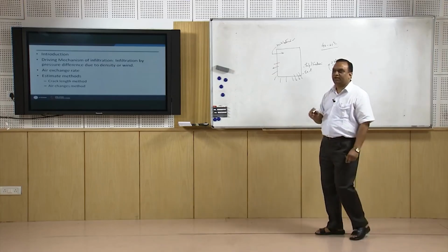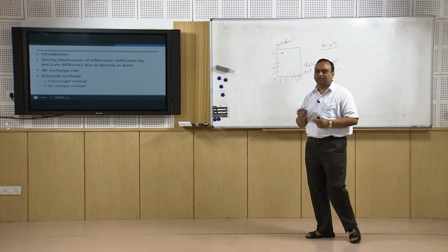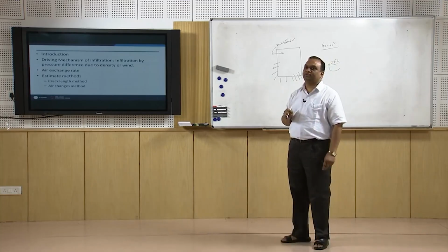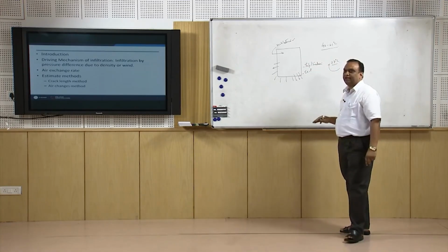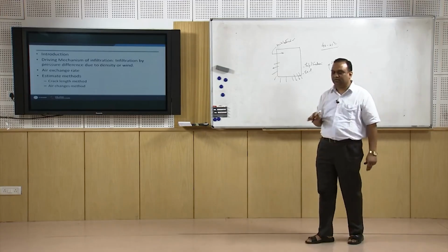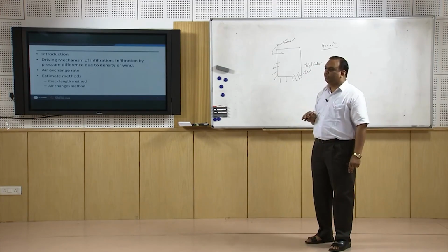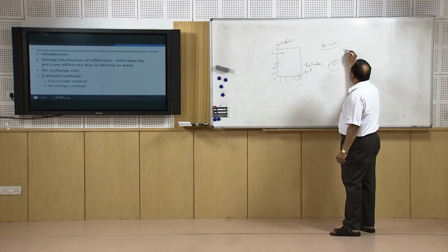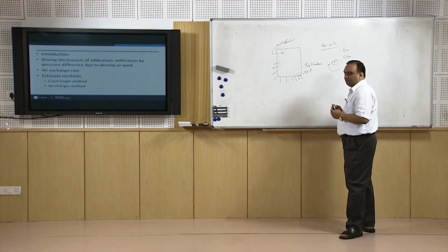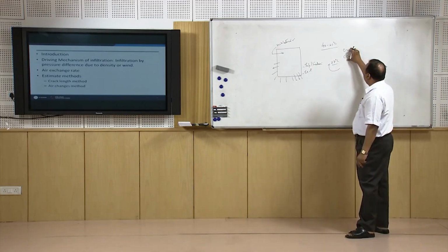So, definitely if I do 100% recirculation of air, the load of the air conditioning coil or system will be less, but at the same time I will be losing the quality of air inside the room. And the main problem with the quality of air will come with the scarcity of oxygen and excess of carbon dioxide. Both have a very harmful effect on human health.